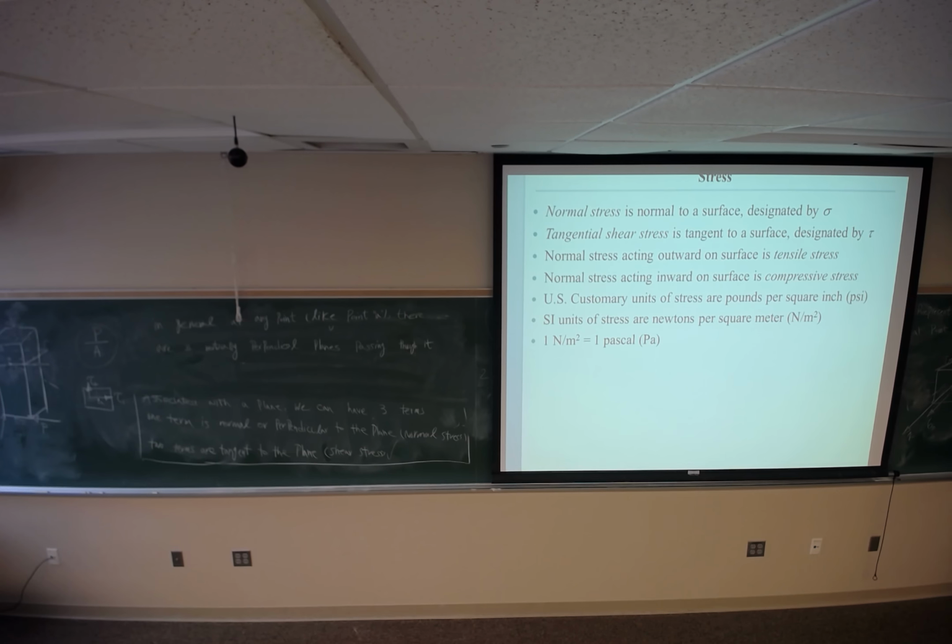Done with this one. For this plane, which is the last plane, this shear stress is going to get the subscript of z, and second one is x. This one is going to get tau z, it's going in y direction, tau zy. So now I'm done with the state of stress for a general point like A.